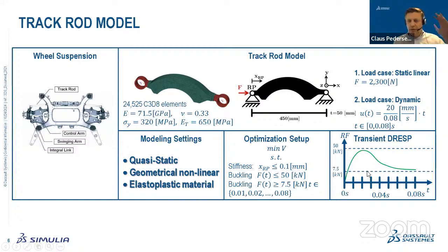So if you look at this green curve down in the corner here, then the idea is that when you have a misuse load case, then it should start buckling. And so all the other components in this system are then staying untouched. And this buckling load should then be over a certain limit. And also, when it's actually buckled, then everything doesn't fall to the ground.